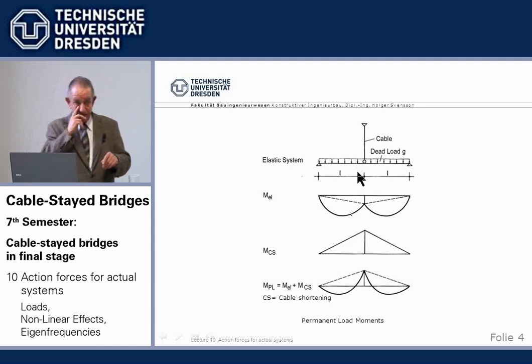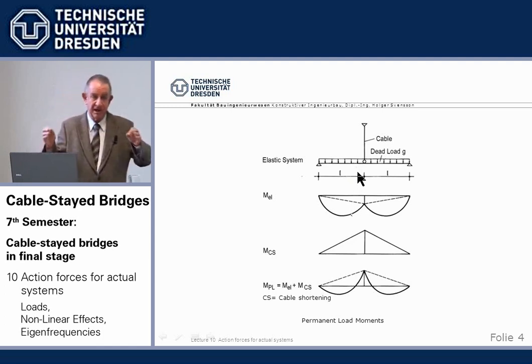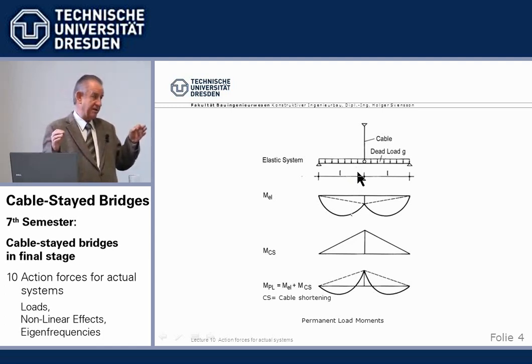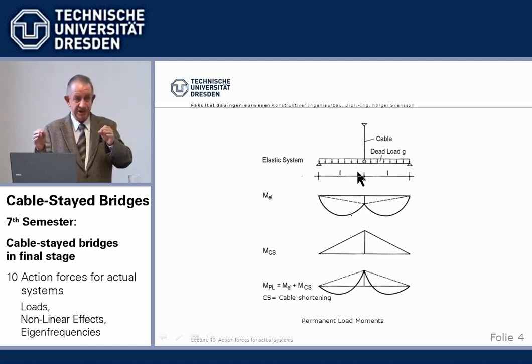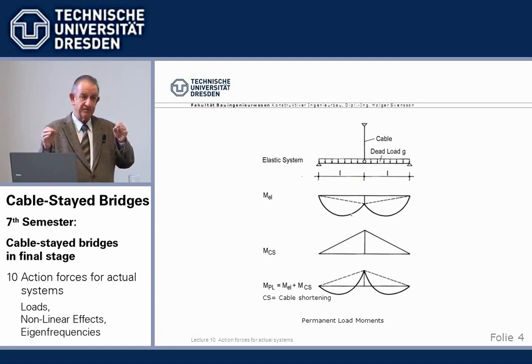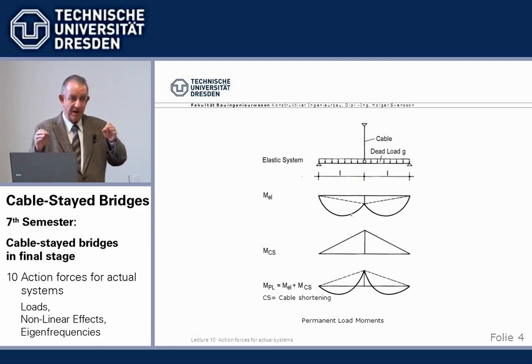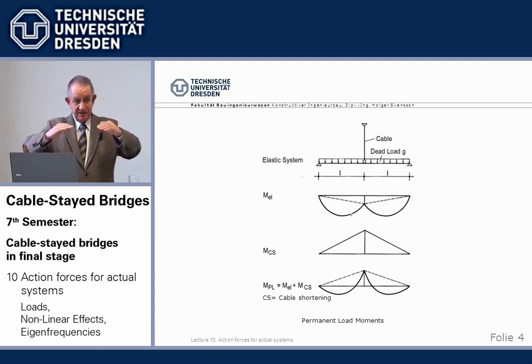So, on site, where we have only elastic cables, we achieve our desired run of moments similar to those of a rigidly supported beam by applying, first of all, the dead load to the true elastic system by computer.